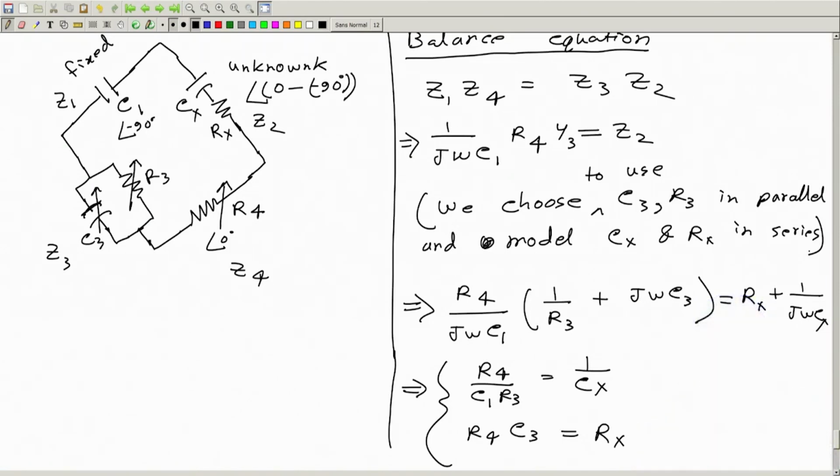And we are giving you practical situations under which this type of scenarios may arise, like when we are measuring an unknown inductor, but we do not have a standard inductor. So, what was the solution? The solution was the Maxwell bridge, which we studied before.